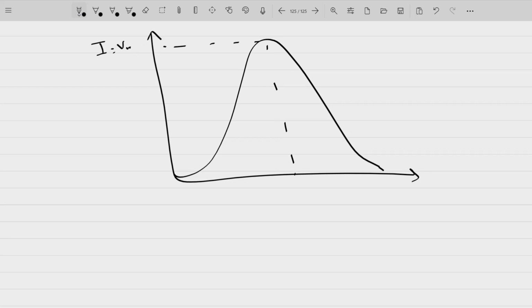I here is equal to Vm divided by R. P average in this case is 1/2 of Vm square divided by R. On either side, P average is equal to P average R divided by 2, and at this particular point the value of current will be 0.707 Vm divided by R. Okay. At the resonant frequency point, it is Vm by R. At this particular point, current will be equal to 0.707 Vm divided by R.